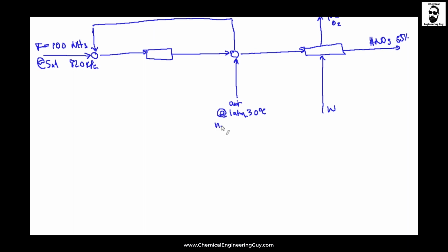This is N1, the amount of O2, because it's oxygen, and I know in air I always get 3.76 times the oxygen of nitrogen. And I'm going to have a little bit of water, so take that into consideration because this is saturated at 50% relative humidity.